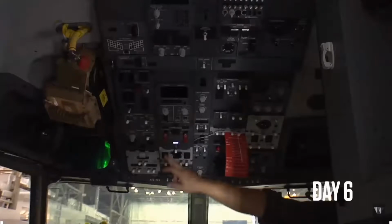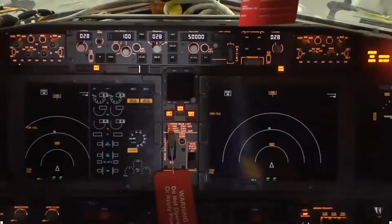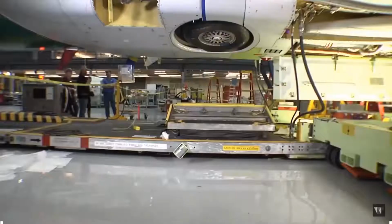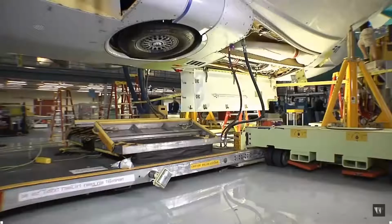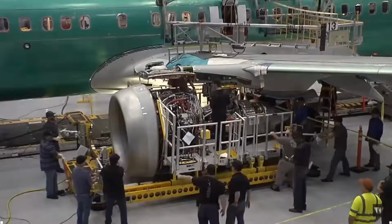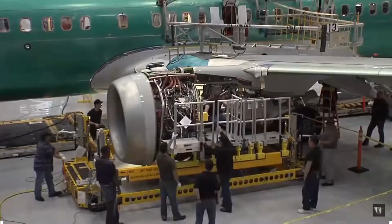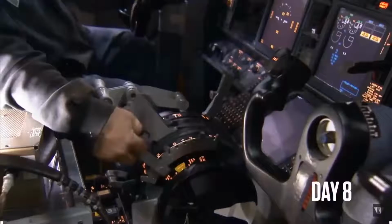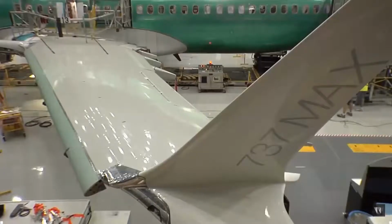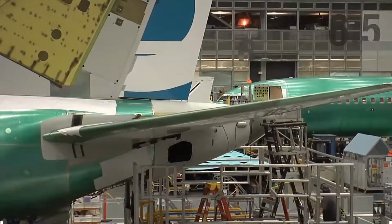Then, on day 6, the plane comes alive. That flashing red light means there's power to the airplane. Large-scale tests are now possible. Like, does the landing gear retract properly? It had better. The next time it's folded away will be when this plane takes off for the first time. Day 7, and the plane's weight is set on its own wheels, and the engines are fixed to the wings along with their own network of wires, cables and tubes. All through the build, systems are checked and rechecked, and day 8 is a critical test of the flight control surfaces, the flaps, and the flight deck itself, the cockpit. All these parts have been checked in isolation. Now it's crucial they work together.